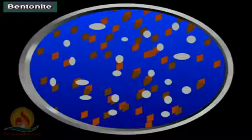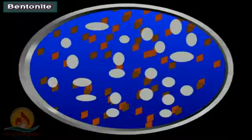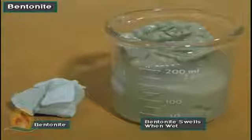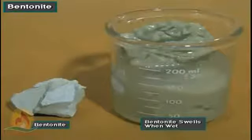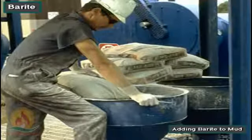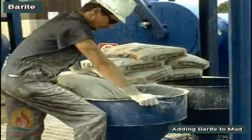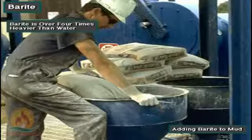In water or oil-based drilling mud, crew members usually add a clay called bentonite or a similar mineral. Bentonite swells in water. Therefore, it thickens the mud, gives it viscosity to help clean the cuttings from the hole and provide other desirable properties. Barite is a heavy mineral. The crew adds barite to mud to make it heavy or dense. Barite is over 4 times heavier than water.